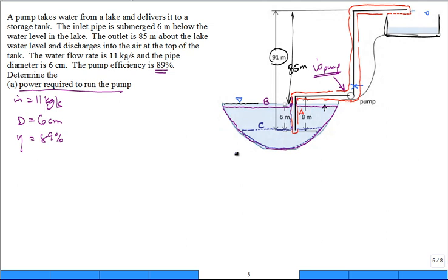Let me analyze control volume B first. Okay. So how does the water get into control volume B? I know how it exits. It's up here, just cutting across that boundary of the control volume. How does the water get into the control volume B? Not so sophisticated. Just rain, yeah. If there's no recharge to the lake, right? What's going to happen to the water level in the lake? It'll drop as I pump it out.